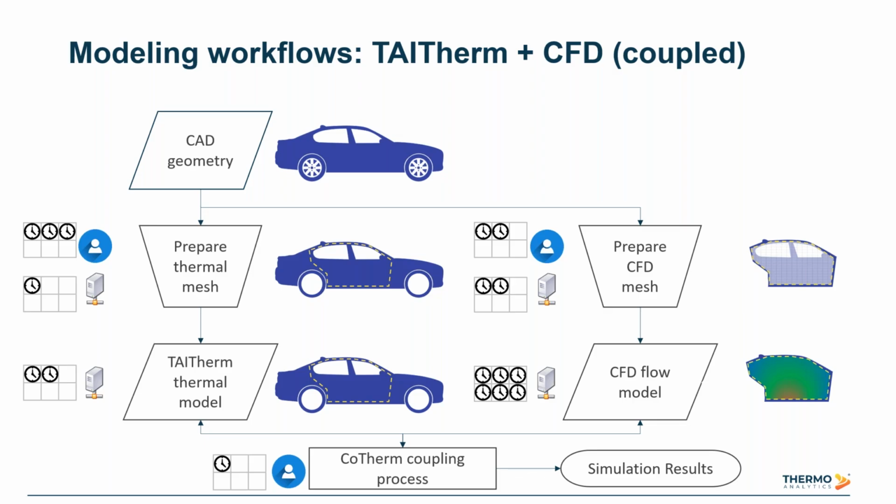So, of course, for applications where we want that fidelity on the airflow side, the other kind of long-standing simulation method would be coupling TAITherm to an external CFD model. And that's going to be associated with some additional mesh preparation for the CFD model that often would be split off from the thermal geometry preparation at some point in the model workflow. That would be associated with at least some additional user time and computational time to generate the mesh. Once we've got that, that'll give us a nice 3D representation of the air inside the cabin, but that's of course going to add a substantial amount of computational cost to what TAITherm is doing on its own.